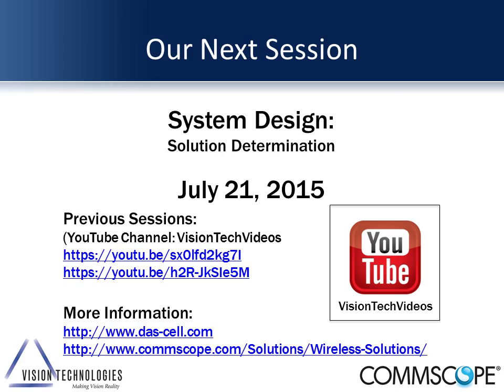Yeah, so the differences and special considerations regarding public safety versus commercial DAS is a couple of pieces. First, public safety, the radios are a little bit stronger than cell phones, and so coverage requirements are typically down to a negative 95 dBm signal strength, versus cell phones, depending on what measurements you look at, it would be like a negative 75 received signal strength indication. So cell phones typically need a stronger and a cleaner signal than public safety radios.